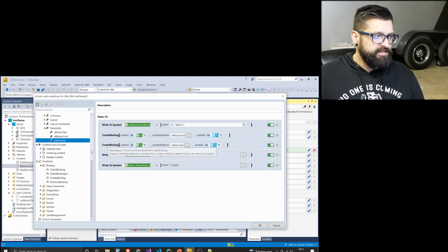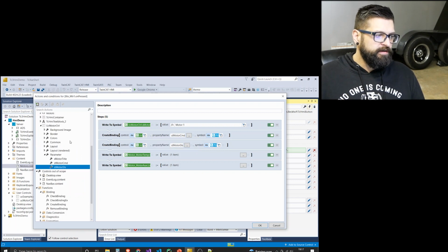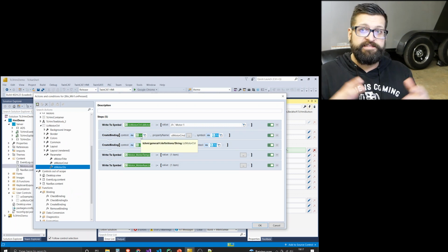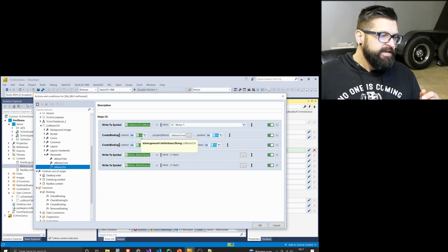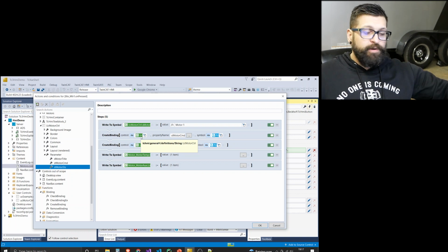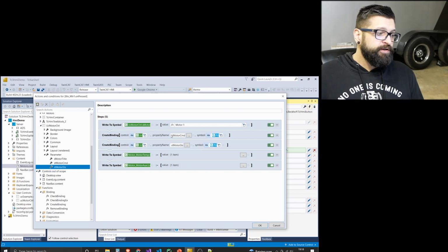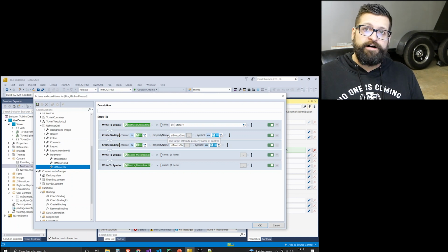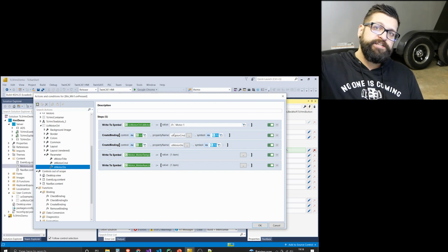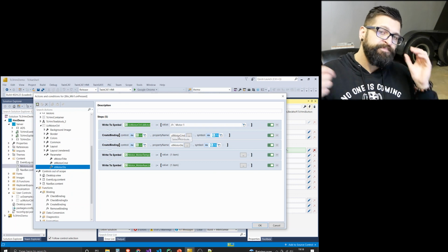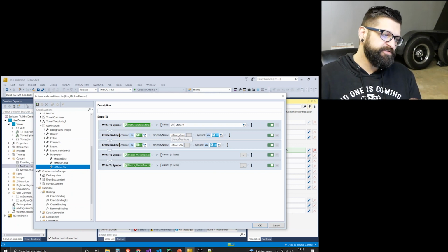UC motor control is the identifier for the instance, the real instance, not the prototype, not the template, but the real instance that I have. And then I've said, well, what property do I want to create a binding on? Well, I want to create a binding on, for this first one, I'm creating it on the motor commands, so the HMI commands back to the PLC. I want to create a binding in that direction first.